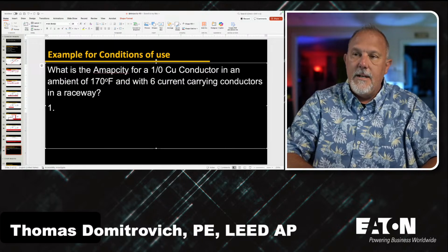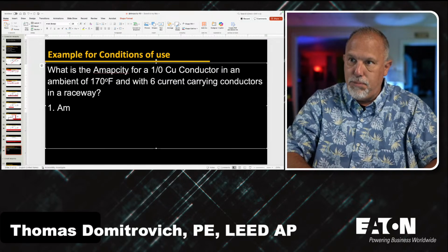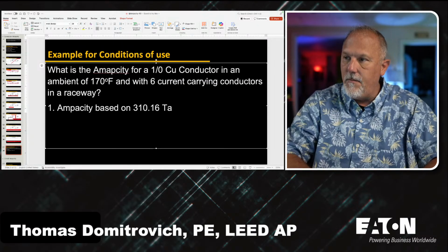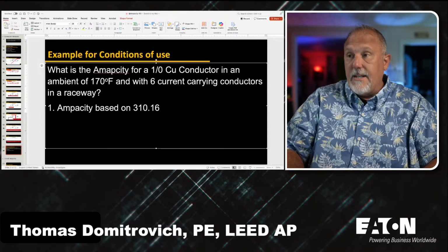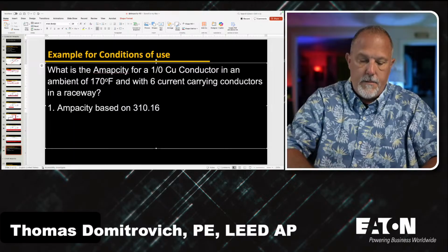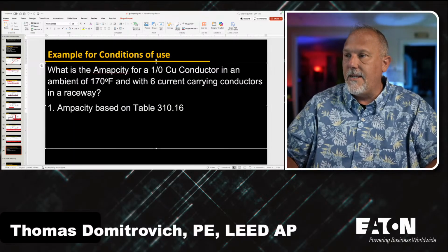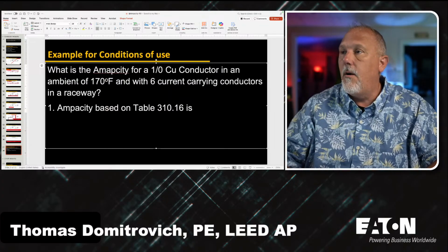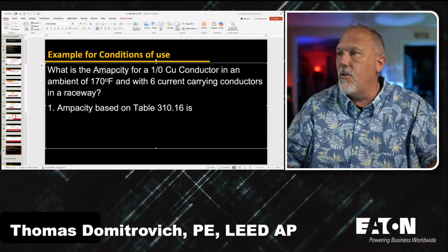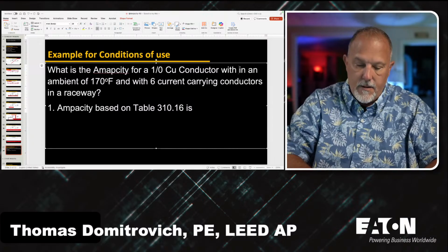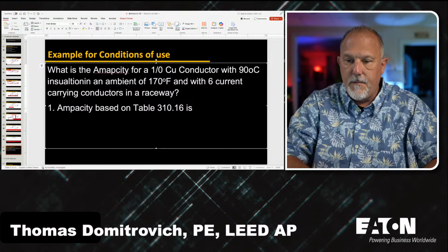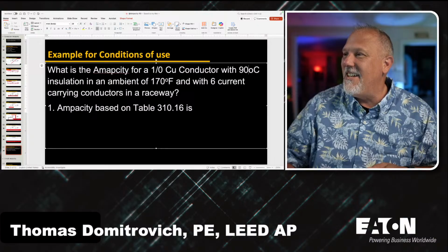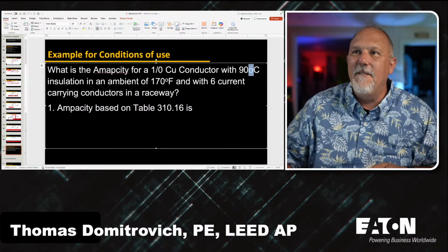The ampacity based on Table 310.16 is, for a conductor with 90 degrees C insulation, ... Joe Bellatoni, I love it. 90 degrees C insulation.